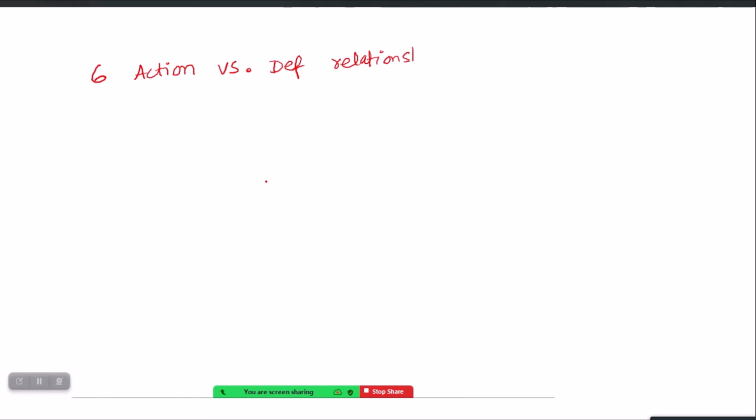and let me just count them again also for you. Let's say that this is your beam or any, let's say, frame element, it is going in that particular direction. So there will be two cross-sectional axes, let's call them 2 axis and 3 axis, and 1 axis by default is the longitudinal axis. If I talk about the ETABS or SAP 2000's local axis orientation, so then 2 and 3 axes are actually the cross-sectional axis and 1 is the longitudinal axis.